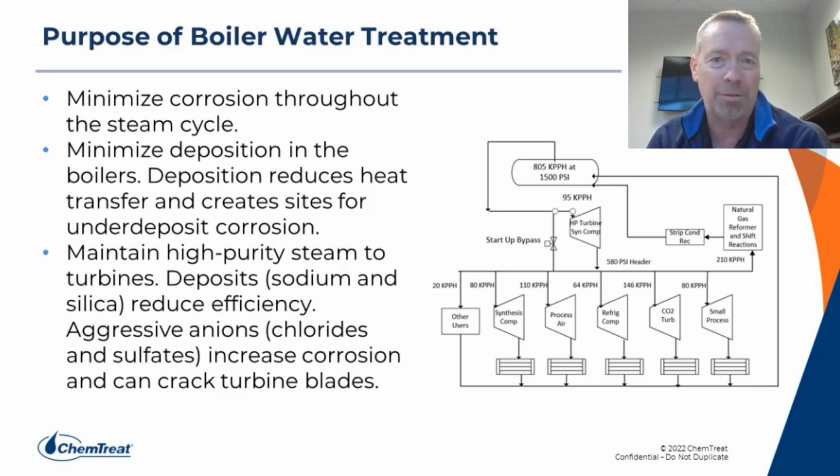Actually, the only really true corrosion inhibitors that we add to the steam cycle in some cases could be a film forming amine. We don't discuss it much today, but we do see film forming amine use very prevalent in the power industry, and it's growing in our industries, in the chemical, petrochem, and refining industries as well. And then the oxygen scavengers themselves, some of the organic oxygen scavengers do have some slight passivation properties. But again, really the work is done up front, and we'll discuss that in more detail.